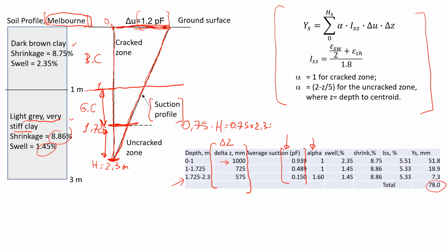So if we go back to that first layer of brown clay, here you will see that it will be 0.5 meters in the middle of the clay layer, and we're going to get this value of suction, and we're going to estimate that. The way that I did is I look at this triangle and at this bigger triangle. What if we have this value as x?